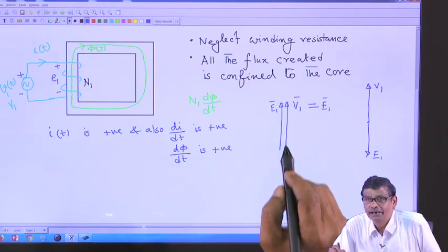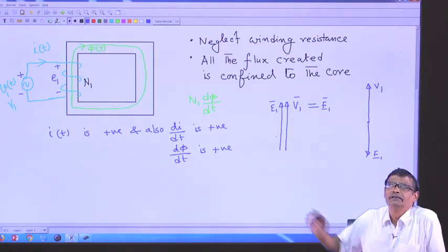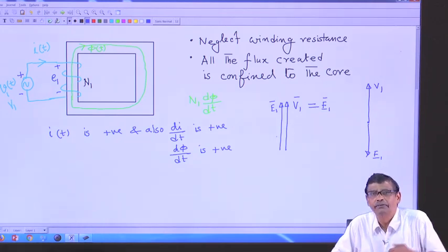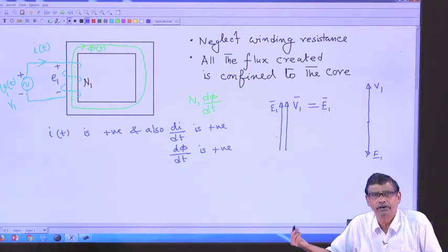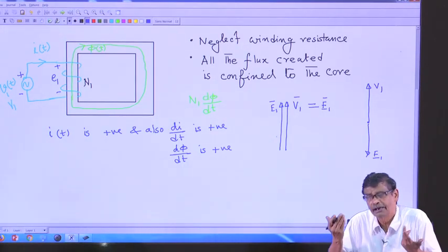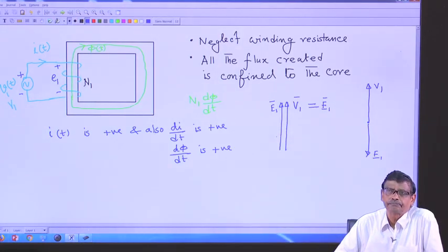So, I will go by this way of looking at things, because if there are two quantities i1(t) and i2(t), some currents in different branches, and if they are in time phase, that is, when i1 attains maximum, i2 also attains maximum, they are in phase. So, draw along the same line, why not? So, mind you, this is the thing.